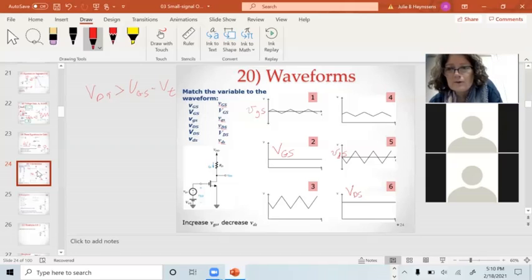The smaller signal here is going to be little v, big G, big S. And this one will be little v, big D, big S. Okay, 2 components. The DC part sets where I am on that voltage transfer curve, and the AC tells me what my signal swing is around that DC operating point.